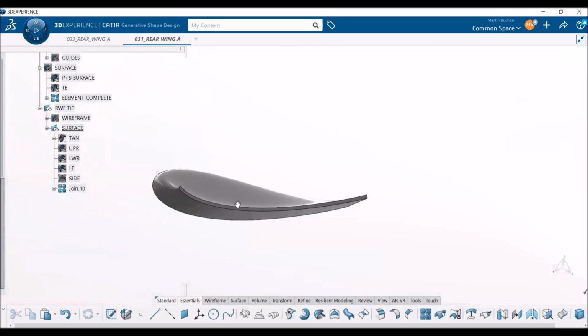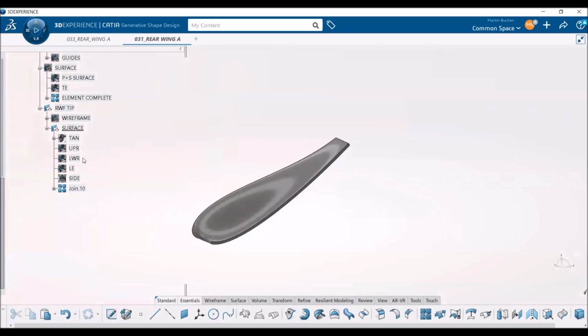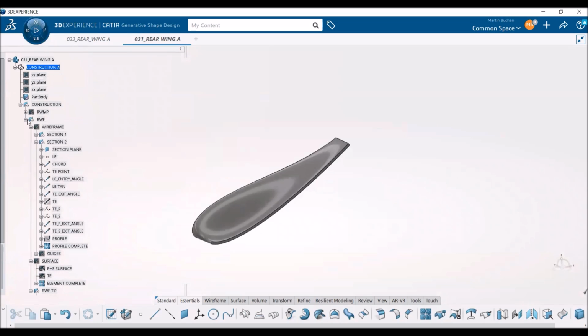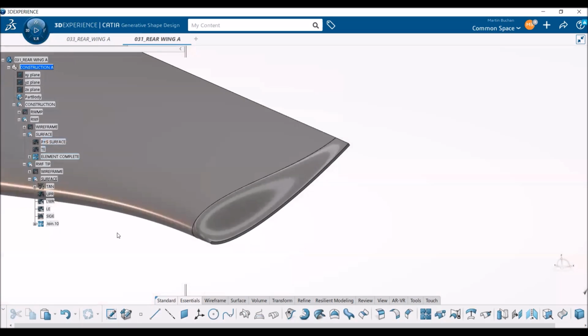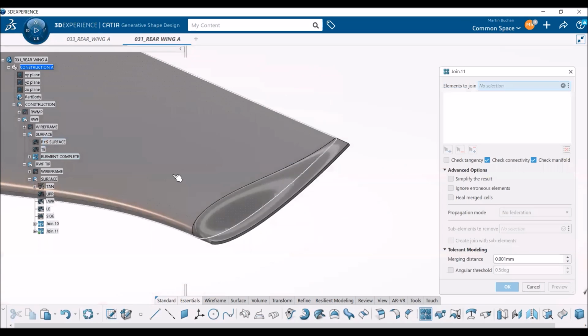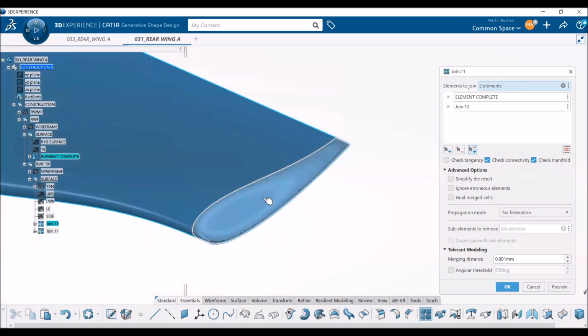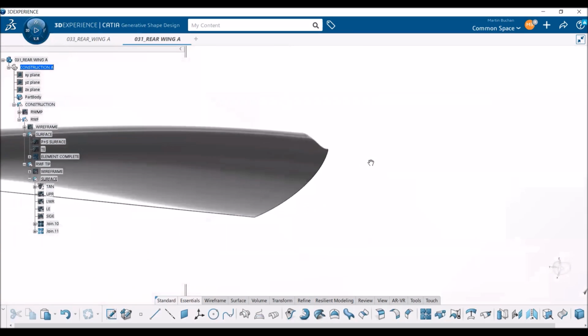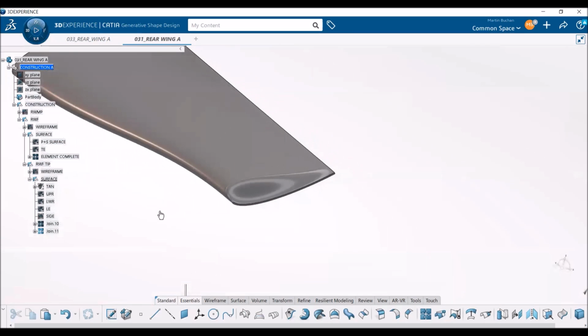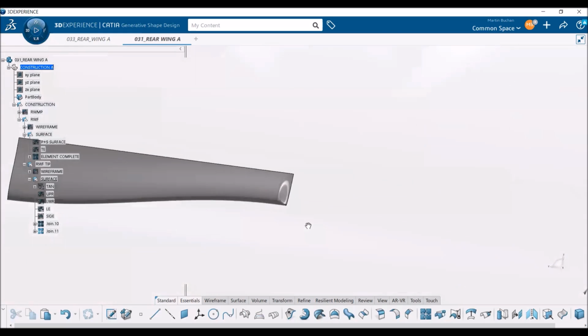One thing we would still do then is the trailing edge surface, but that would be a pretty easy one. What's interesting for us is now if the tip is tangent to the rest of the flap, so now we just join both elements and you can see that it's tangent because we built everything tangent. The only problem with this feature is now that it's only 20 millimeter wide and it's quite a dramatic change of surface, so